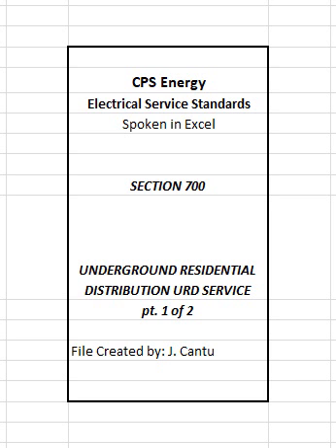701.2 Easements for underground facilities. CPS Energy facilities including primary distribution, transformers and pads, secondary laterals, and secondary enclosures will be installed in easements as determined by the CPS Energy Customer Service Representative. CPS Energy facilities may also be installed in alleys, streets, or other public right-of-way. Note: CPS Energy will not permit temporary or permanent structures to be placed in a manner that will obstruct CPS Energy access for maintenance or repair of CPS Energy facilities, even if they are not located in an easement.